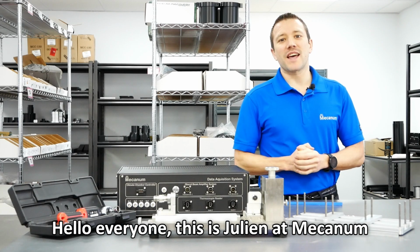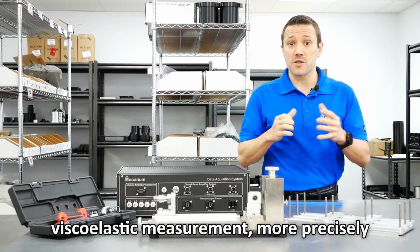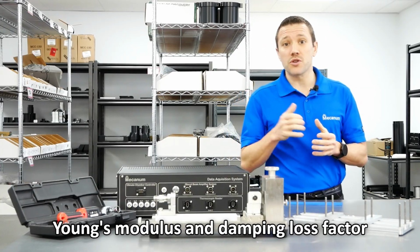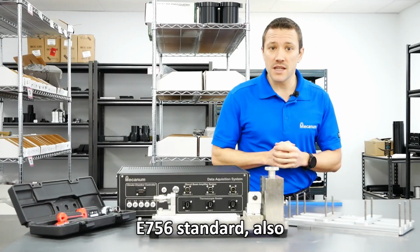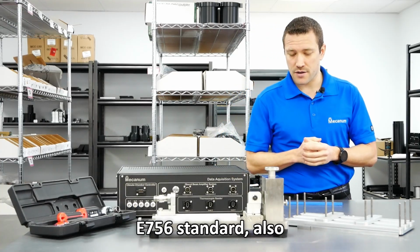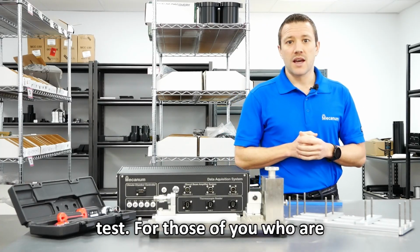Everyone, this is Julian at Mecanum, and today we are going to talk about viscoelastic measurement, more precisely Young's modulus and damping loss factor measurement using the ASTM E756 standard, also known as the Oberst beam method test.